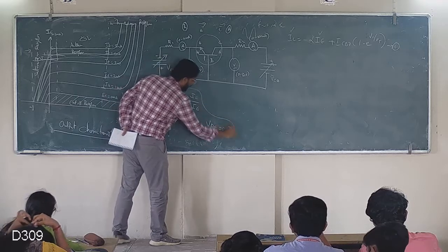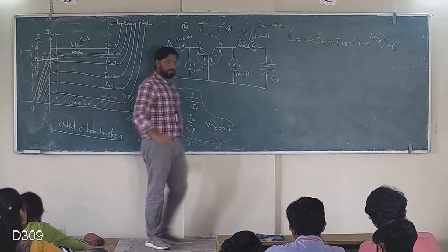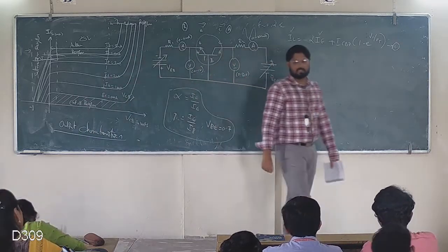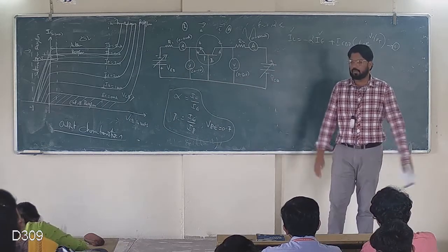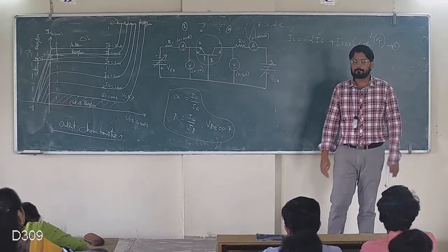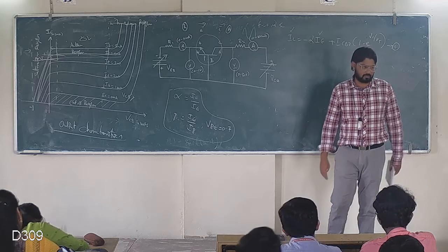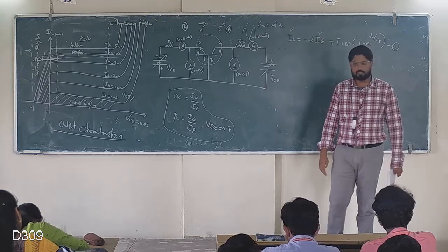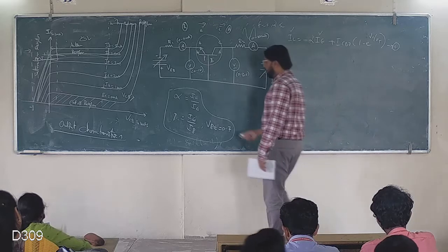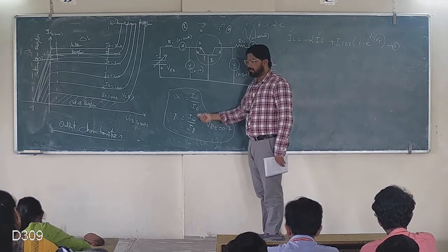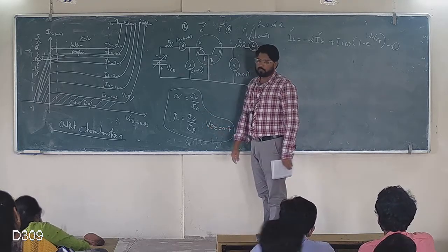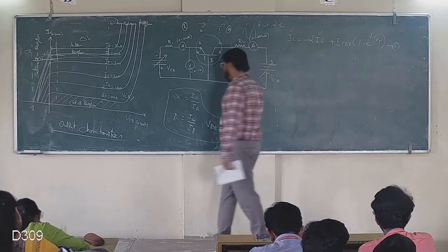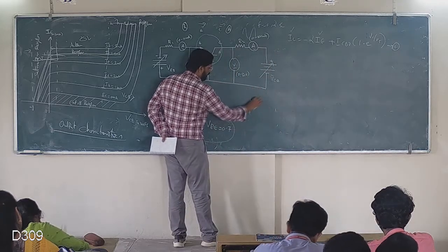So these three are the transistor parameters. If you take any transistor, these three are fundamental, like a birth certificate. You got the point? Like a birth certificate, right? So what is alpha? IC by IE. What is beta? IC by IB. VBE is equal to 0.7 for silicon. How do I remember? Just draw the symbol like this.